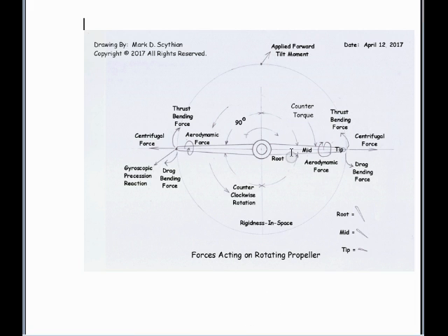So let's say it's fixed pitch, you don't have any variable blade pitch swash plate on it, just something with few moving parts. So you'd have computer control, so when you put the throttle in, it would rotate these all equally, you'd get liftoff, and if you wanted to tilt forward, you'd have a higher RPM in the two rear propellers, canceling each other out, so there's no torque and no precession going on, and this would cause a tail lift greater than the front lift, causing the tilt to happen. And that's applicable to the roll as well as the pitch.